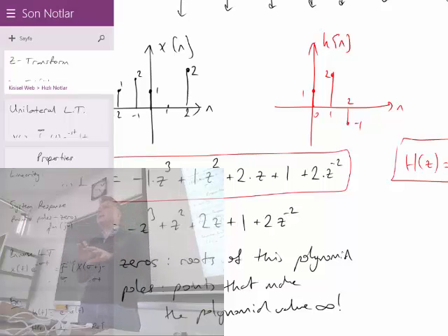The algorithm to write a convolution, if you want to write a program, a C program, for example, to perform convolution, that will not be very difficult. You flip around and you slide, you overlap. So that is the methodology to apply polynomial multiplication, as a matter of fact, not the other way around. For humans, polynomial multiplication is quite easy to understand what it means, but algorithmically in the computer it's easier to convolve. So they do polynomial multiplication using convolution.